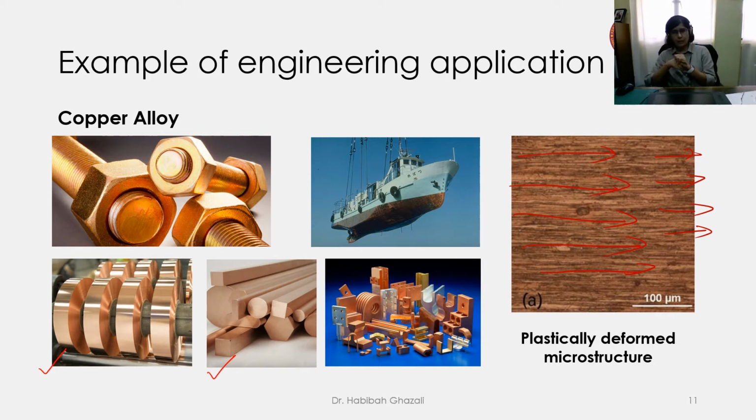So what is anisotropic? I have explained in class a few times. Anisotropic is when you have a microstructure that is very directional, so when you test it from different directions, it will give you different properties. For a lot of mechanical engineering applications, we want to avoid this. So I think I need to explain a little bit more about anisotropic materials.